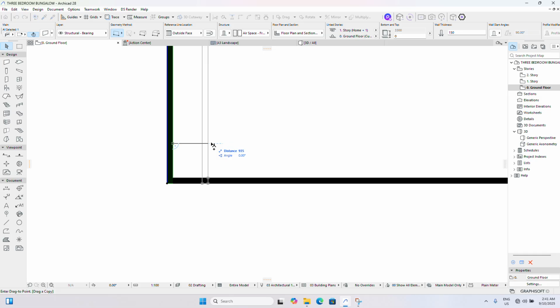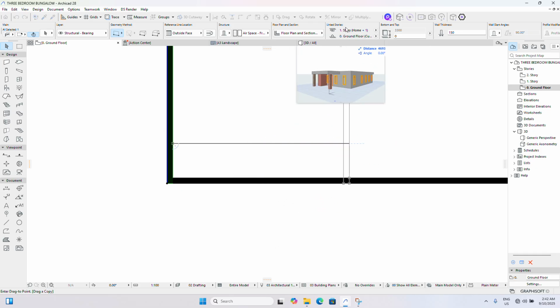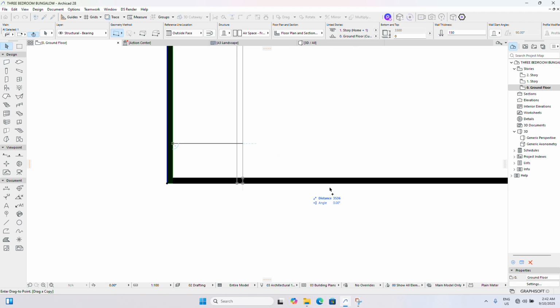Now if I click on this wall, I will drag. Now if I drag, I will hold my shift key. Holding my shift key is making sure that this thing is in a straight line. If I remove my hand from my shift key, it can move up, it can move down. So holding my shift key will make it straight. So even if I move my hands anywhere, it will remain straight. So look at it. I will now press R. R means to edit the distance. I'm editing the distance.